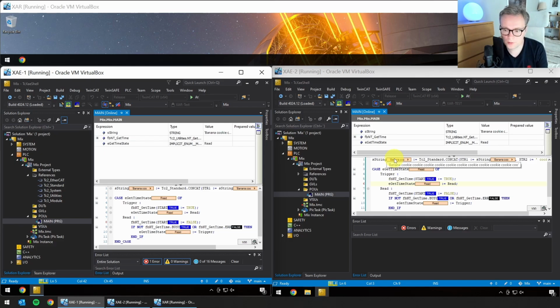This is basically what you need to know to make sure that you can always rebuild the application using the same versions of TwinCAT, which is quite important, because you might keep track of this in a month or two, you might remember what you're using, but if you work with many machines, and especially if you worked with 10, 20, 30 machines and over 5 or even 10 years, then this is going to get a mess. So it's always good, when you're getting close to the delivery of the machine, to just freeze everything, freeze the libraries, freeze the compiler, and make sure everything is committed, create releases. You can create formal releases of your software in Git and make a version of the software and put it on the machine. Then you're clean and can always go back to rebuilding your whole application.